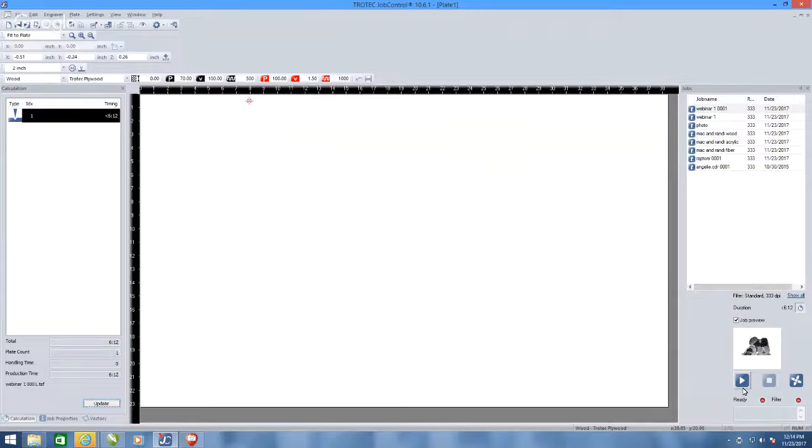You can't get photos on a piece of glass unless you use the pre-mask, which is the white transfer mask that we sell at the office here. You place that on the glass and then you etch through it, using the image exactly as if you're doing it on acrylic. So I've gone in and done a mirror image of the image so it's inverted, and now I'm going to etch through the transfer mask, which gives me a nice fine finish on the actual glass itself.